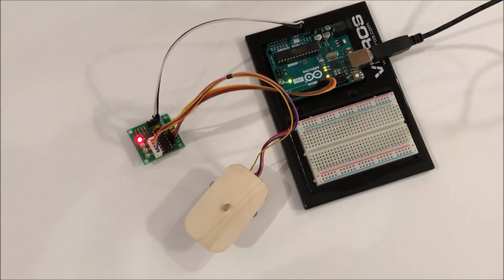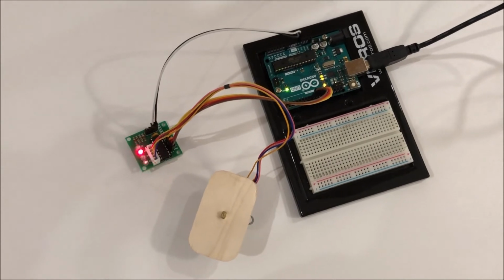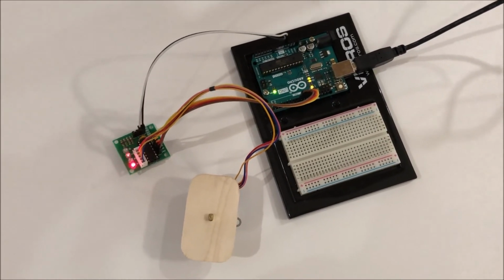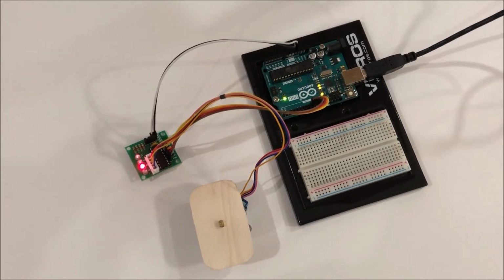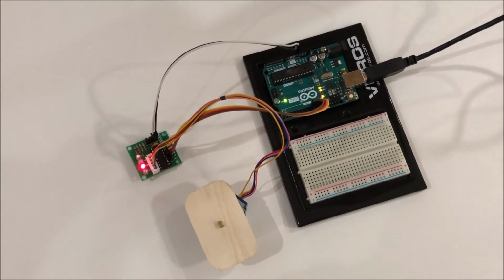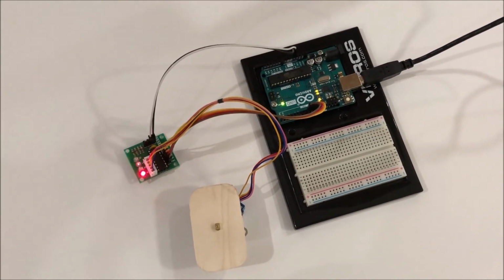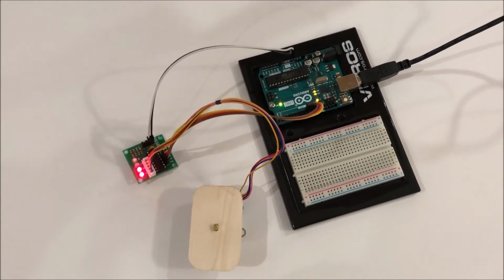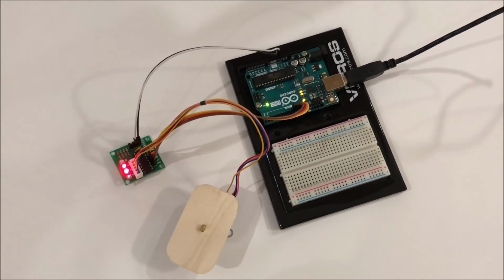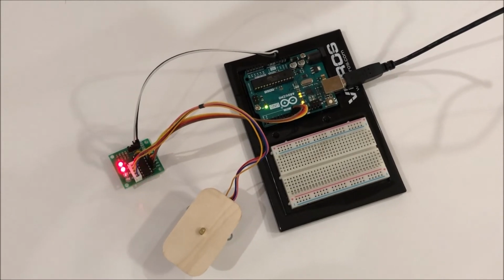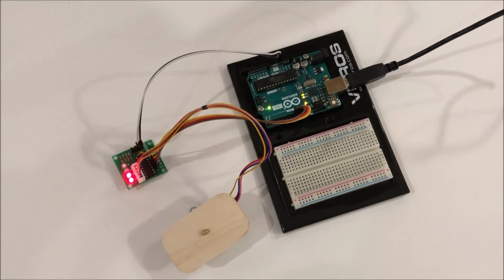Well, I swapped the 2 wires and my stepper motor's moving again. So, to repeat, what did I do? I went through a list in my head of the things that were likely causing the problem. I then thought about which ones were easiest to check and checked those first. I used a little bit of logic to divide the circuit from the code, realized that my code was probably good, and then went back and checked the more difficult circuit looking at all the connections.